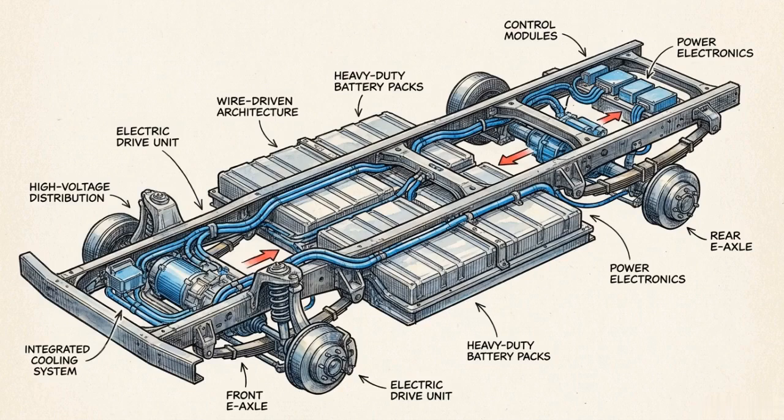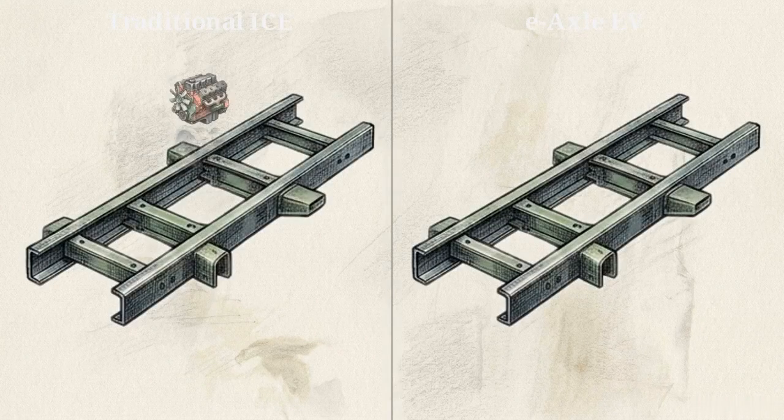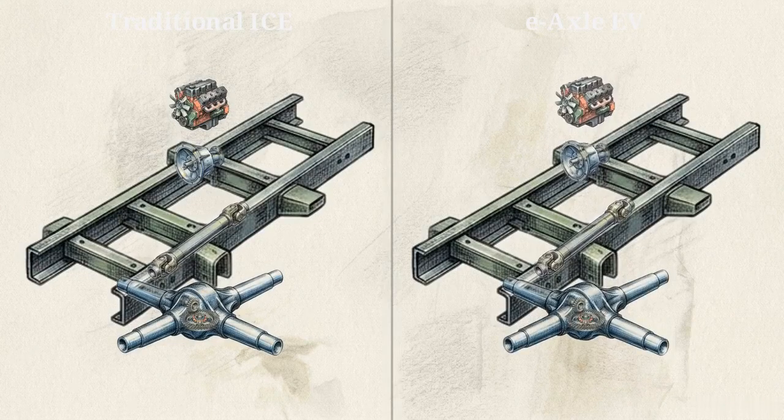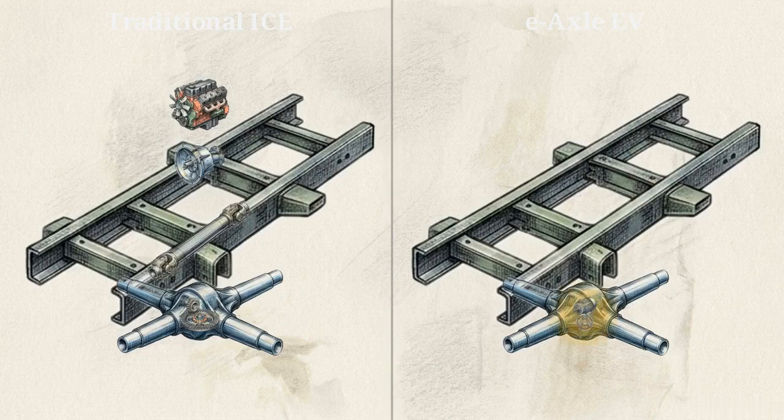Today, commercial drivelines are undergoing a massive transition as electric vehicle architectures begin replacing heavy internal combustion layouts. This side-by-side comparison contrasts a traditional layout with the modern E-axle. In an EV configuration, the massive longitudinal propeller shaft is completely eliminated. The E-axle integrates an electric traction motor and planetary gear set directly into the space where the traditional differential sat.